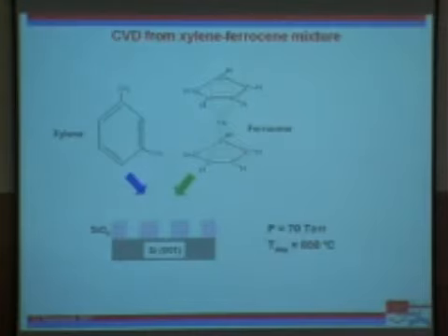So here we resort to chemistry, where nature does most of the work, and we just have to get lucky by trying the right kind of things. And we use a precursor where we have a carbon source and a catalyst which is delivered from the gas phase. And this catalyst selectively interacts with silica, SiO2, to the exclusion of silicon, and produces growth of carbon nanotubes only on silica.